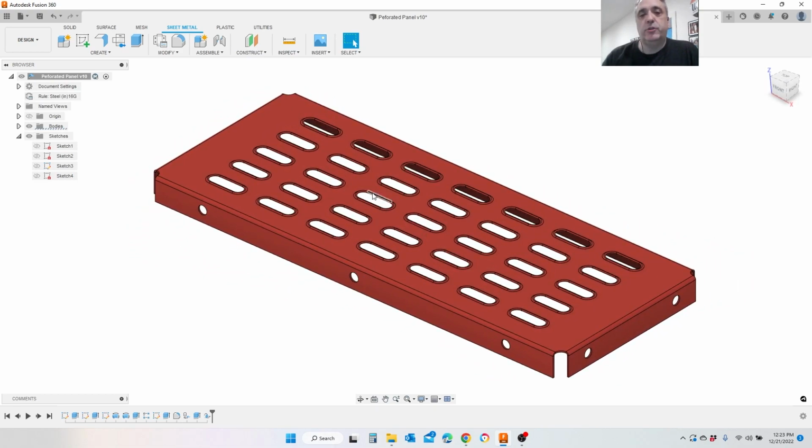And again, you can use protrusions like this to stiffen anything like webbing within aircraft, but also lightening it as well. If you need to get it to be lighter but still stiff, you can put protrusions in this. You can make them whatever pattern you want. Definitely leave some comments if people have some thoughts or ideas on different patterns or methods or flow methods. This is how I would go about it.